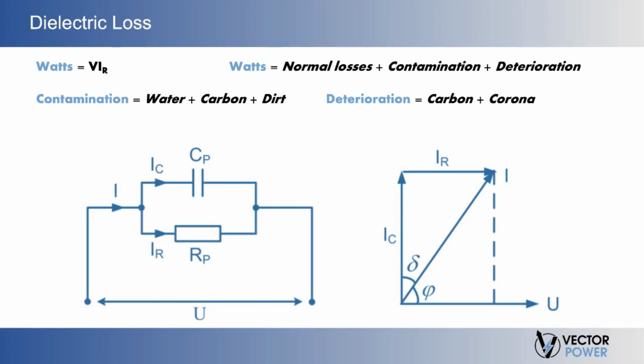Dielectric loss quantifies a dielectric material's inherent dissipation of electromagnetic energy, for example, heat. It can be parameterized in terms of either the loss angle delta or the corresponding loss tangent of the angle delta. Both refer to the phasor in the complex plane whose real and imaginary parts are the resistive loss component of an electromagnetic field and its reactive or lossless component.